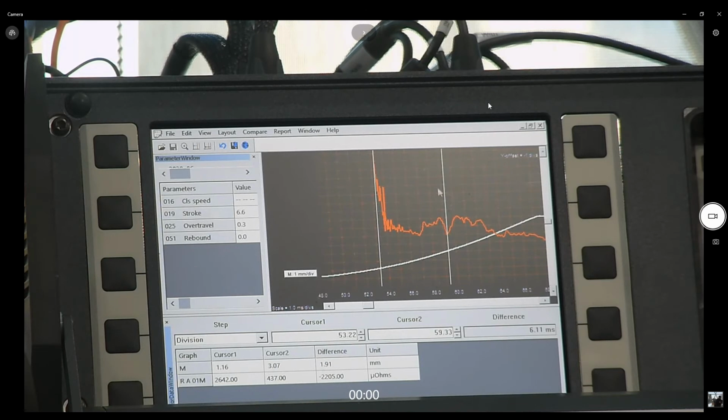So in my circuit breaker analyzer here, in my analyzer view, I can set cursors at certain points in time. Usually I will set these cursors at the start and the end of this jump in resistance for the arcing contact. Now for this AIS or air circuit breaker, it's very difficult to define these two jumps. But for GIS or SF6 systems, it will be very easy to do that. If you already own the DRM or SDRM and you want full training on how to do that, please contact me and I will be happy to give you great detail on how to achieve that, how to connect, and how to perform a test for your SF6 breaker.